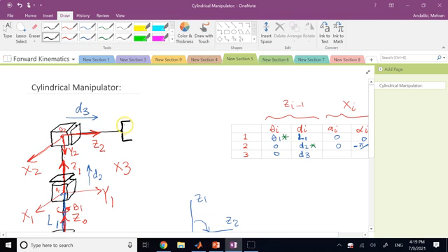It's a fixed distance between the center and the beginning of the wrist. So I would put my origin right here. And then I go with what I had. So I make this Z3, and then it was this guy, which was X3, and then I had Y3, right? So this one was Y3, then I had X3 and Z2 here, okay? So I'm just trying to write it as clean as possible.